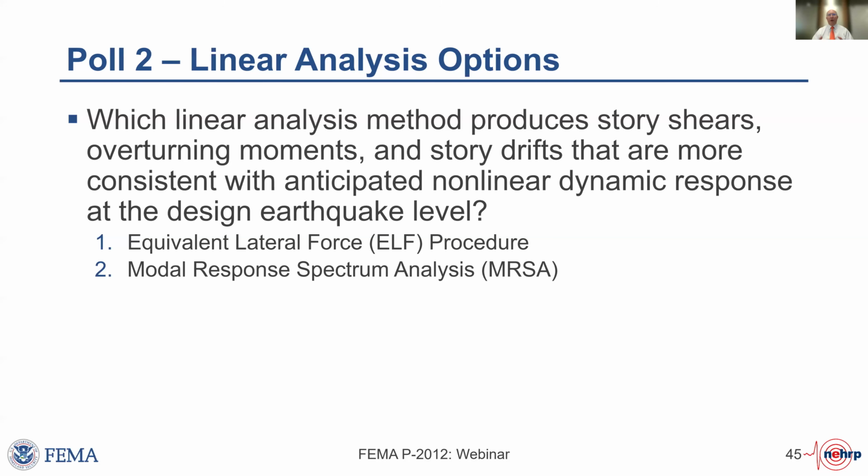The reason being, in part, modal response spectrum analysis is still linear, and when you have an R factor of 5 or 8, the response is definitely not linear, and so the strength matters a lot in a way that the method can't pick up. So ELF does a better job of characterizing the results. It doesn't mean you can't use modal response spectrum analysis. It does give you some insights into the dynamic performance of a building. But the ELF procedure is both more conservative and generally better matches the envelope of results from nonlinear analysis. Great, thanks, Mike. I'll go ahead and close the poll.